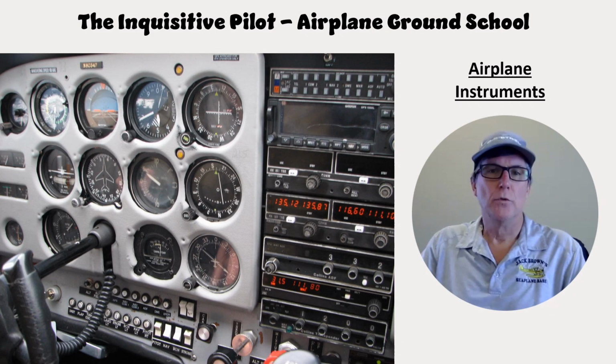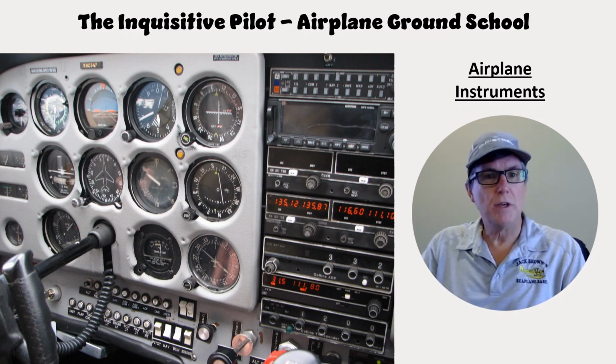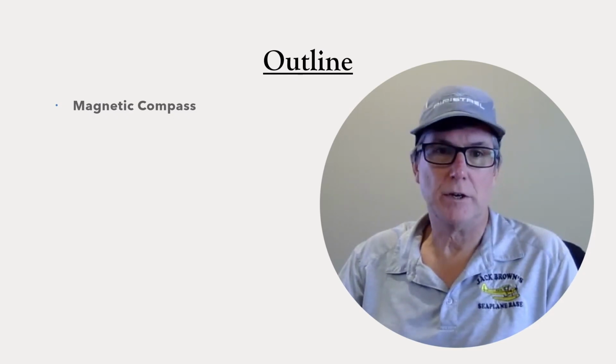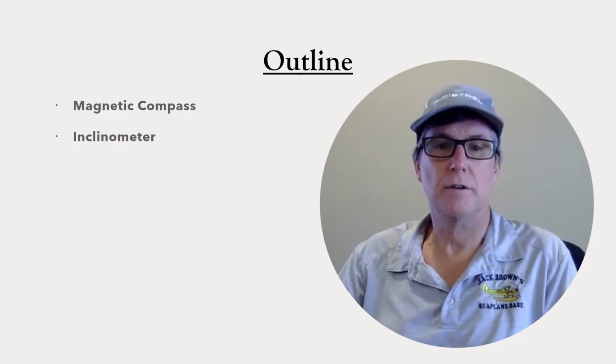Controlling an airplane requires you to take in information about what the airplane's currently doing and what the air around it is doing. You have instruments to provide that information, but with caveats. You need to be able to interpret what your instruments are telling you and understand some of their potential failure modes. The magnetic compass tells you your heading, but it's subject to some errors. The inclinometer tells you whether the airplane is pointed in the same direction that it's currently moving.